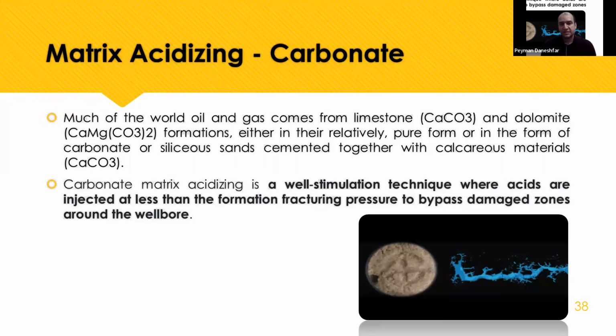Carbonate matrix acidizing is a well stimulation technique where acid is injected at less than the formation fracture pressure. Remember again, the acid pumping pressure doesn't exceed the fracture pressure, to bypass the damage zones around the wellbore.